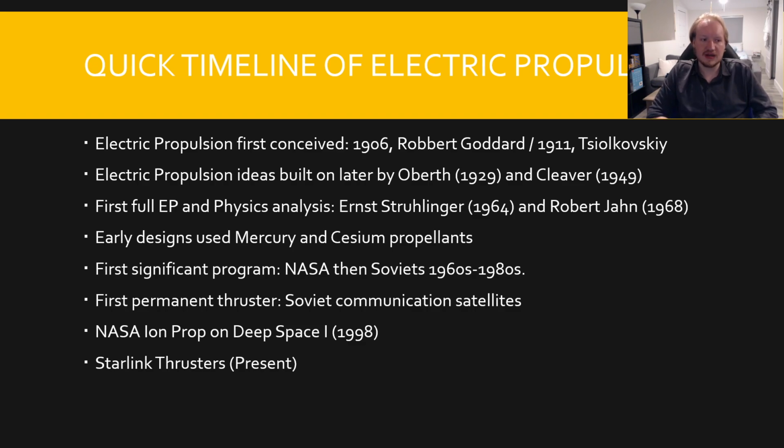The most common metallic propellant we use now is indium. That's used on a lot of these FEEP thrusters, though we tend to use noble gases now. Xenon's the best option, or krypton or argon, or some systems use hydrazine, which is another common propellant, though a lot less efficient than those noble gases, and that's not going to work on some of the more sophisticated systems.